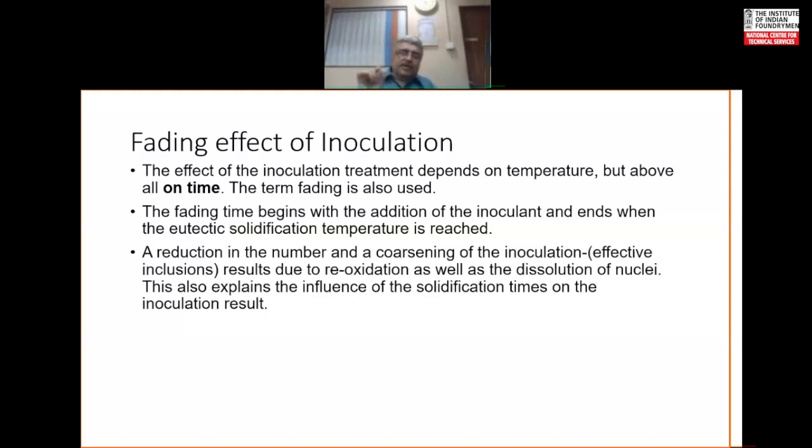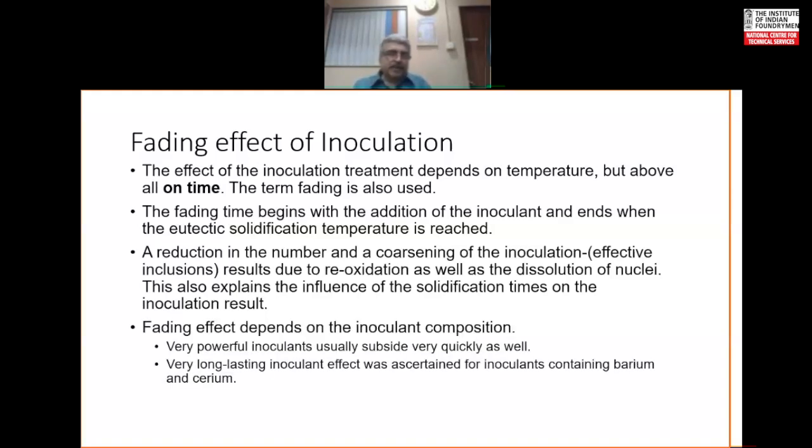There is something called a critical radius for these particles which are forming nuclei; they remain stable only if they meet that radius. Anything below that gets dissolved by the bombardment of the liquid molecules which are roaming around in the liquid metal. The fading effect depends on the composition as well as the size grading.